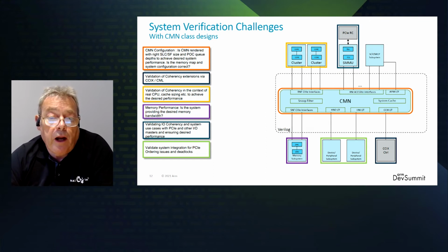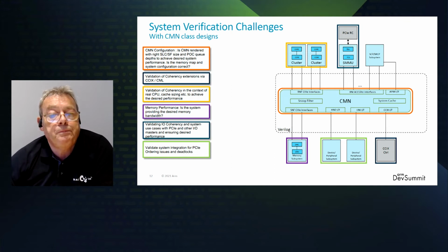The CMN works closely in combination with the memory controller or controllers you plan to use, and so also validating the system memory performance of the two IP together is critical to ensure that your performance issues aren't baked in. It's far easier to test and debug just the CMN and memory controllers as a subsystem than it is to do the same on the full SoC. However, that does require synthetic traffic generators to model the system behaviors and exercise the full range of scenarios.